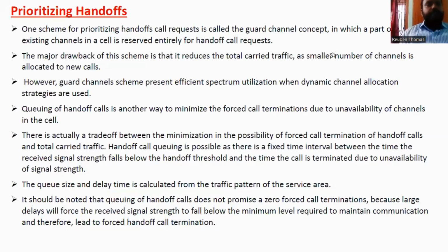So good morning. Today we'll see about the prioritizing of handoff. One scheme for prioritizing handoff call requests is called the guard channel concept, in which part of the existing channels in a cell is reserved entirely for handoff call requests. The major drawback of this scheme is that it reduces the total carried traffic, as a smaller number of channels is allocated to new calls. However, the guard channel scheme presents efficient spectrum utilization when dynamic channel allocation strategies are being used.